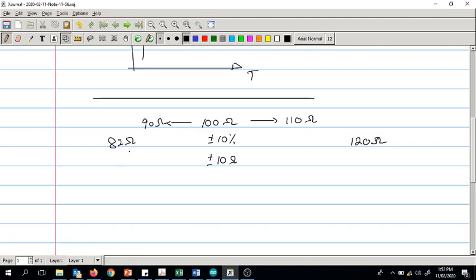That is a requirement. Now if this had plus minus 20% error, then it would be from 80 ohms to 120 ohms. Now you can see 80 is less than this, 120 is equal to the next value, which is an overlap, which is not possible, right? So that is why they say, okay, with the E12 series you can have a tolerance of 10% maximum. You can't have more error than that.